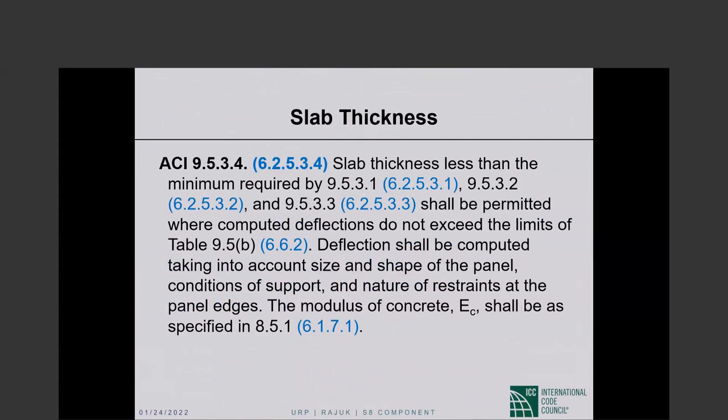Now, slab thickness less than the minimum required shall be permitted where computed deflections do not exceed the limits in table 9.5b. This we saw for beams.